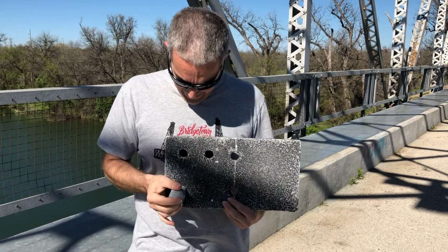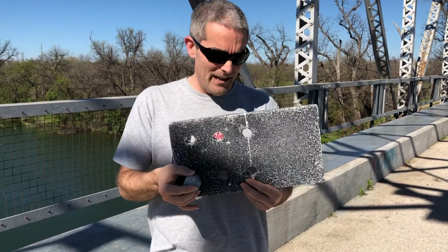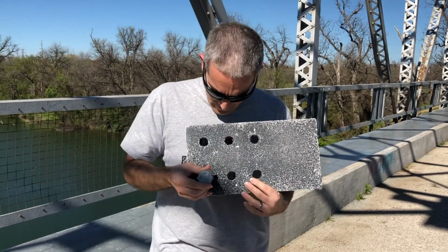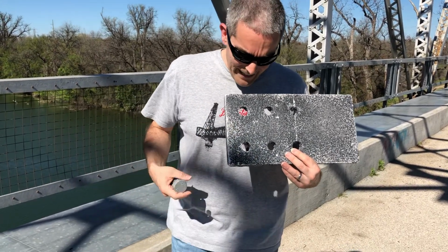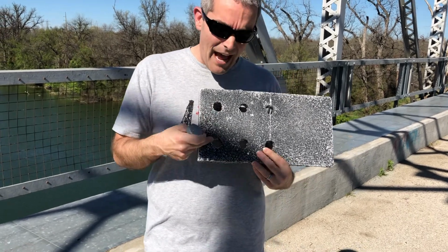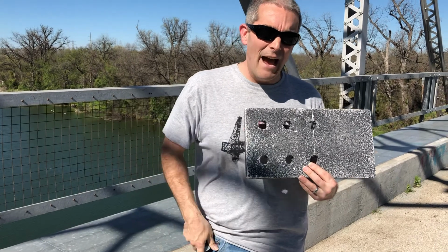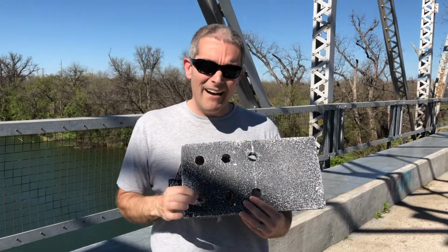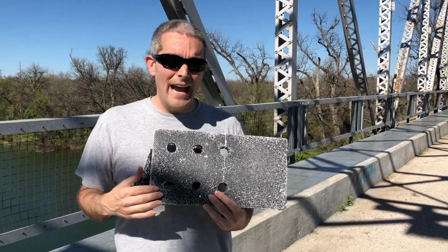And as you can see, it doesn't really fit well. I can force it through because this is styrofoam, but you can see that it's going to cause some sort of problems in there. So I can't use the same diameter hole as I use for the bolt. I have to drill a larger diameter for the hole. So that's why we have the 1/16 inch extra for the hole diameter.